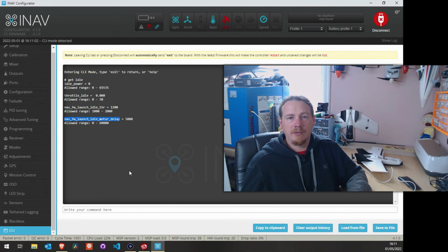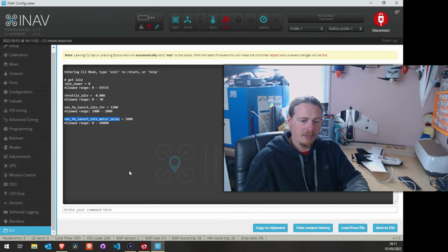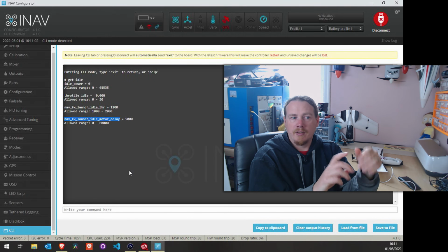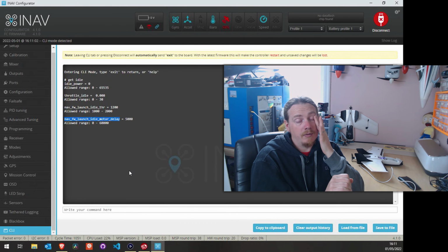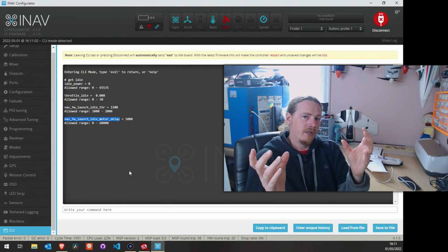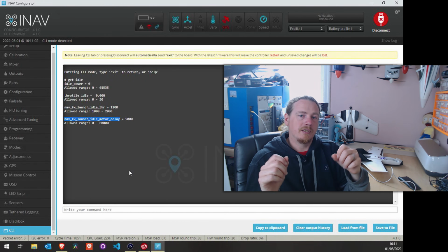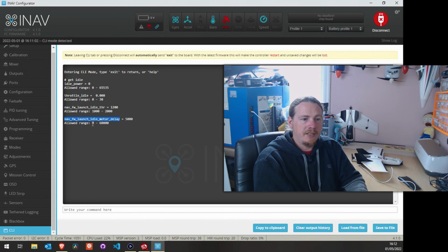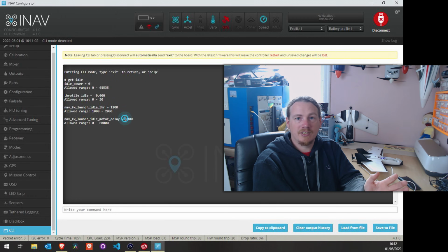What this allows you to do is have your transmitter on the floor, get everything set up. So you enable launch, arm, set the flight mode, raise the throttle. Normally at this point the idle would start, but with this set it doesn't. What you can then do is pick up the model, and after this timeout the idle starts. And at that point you can throw the plane, and it does work really well. It's a very handy setting. So you have a range here of 0, which is off, to 1 minute. So you can have up to a minute of idle delay if you want. I've got mine set to 5 seconds.